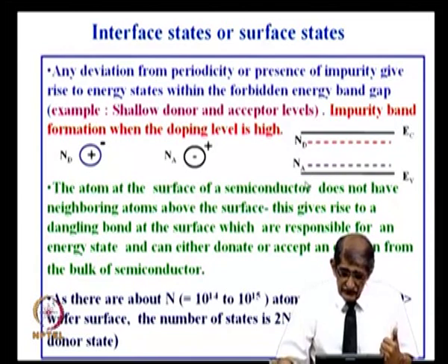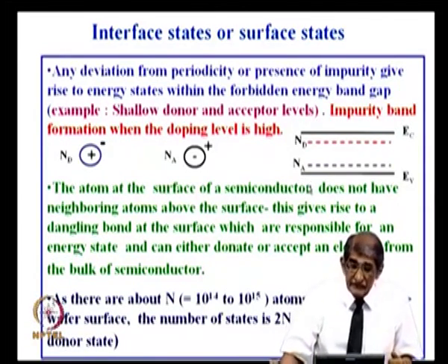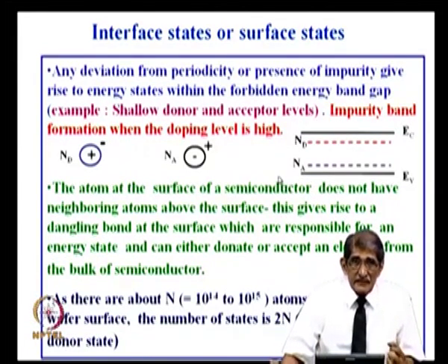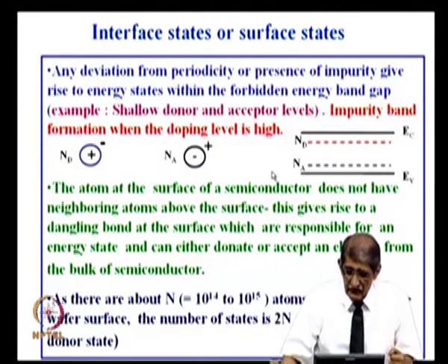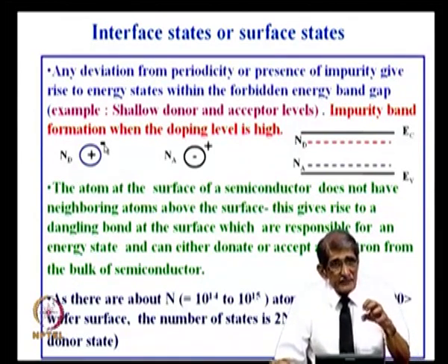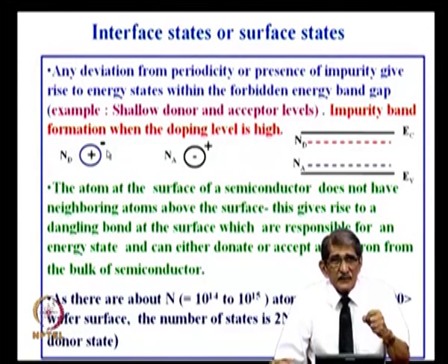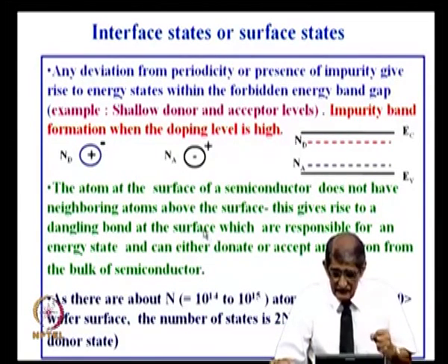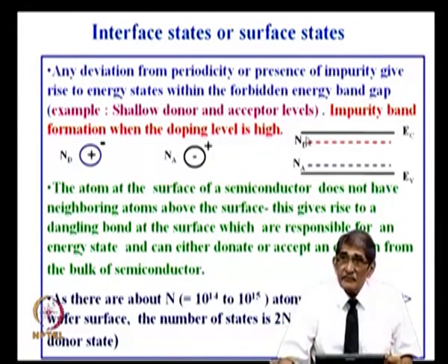Now, let me ask you, if you knock out electrons from the valence band, that is the electrons from the bond, you have to apply an energy equal to 1.1 electron volts. That is why the conduction band valence band difference. But if the silicon is on the surface, from there if you want to knock out electrons, you may not require as much energy as is required for the band gap, but it will not be as small as what you require for this pentavalent material.